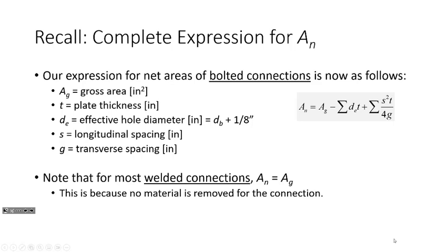For welded connections, the net area and the gross area are the same thing, at least for most fillet welded connections, because you're not removing any material. And just so you are aware, when we get into welds, 90% of the welds that we as structural engineers design are fillet welds. The other are groove welds, and to be frank, we don't really do a lot of hardcore design of groove welds, but we'll talk about that when we get into it. Because groove welds are really a lot more of a specification thing than an actual design thing. But we'll talk about that later.